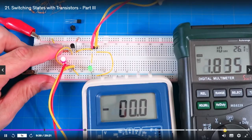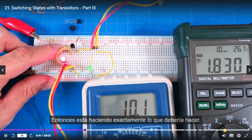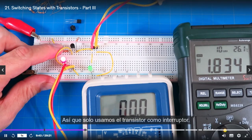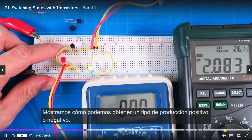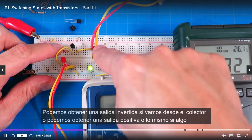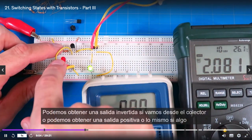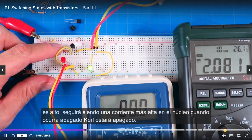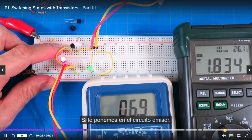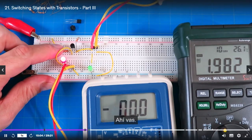All right. So it's doing exactly what it should do. So we just used the transistor as a switch. We showed how we can get either a positive or negative kind of output. We can get an inverted output if we go from the collector, or we can get a positive output, the same. If something is high, it'll remain high. If current's on, current will be on. If current's off, current will be off, if we put it into the emitter circuit. All right, so there you go.